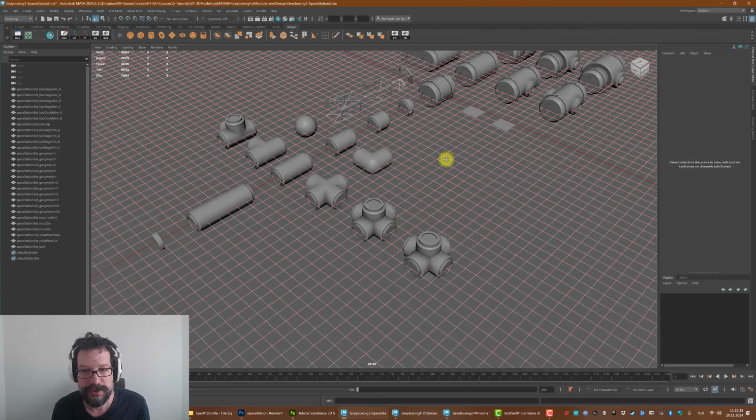So in order to do that, we have to export this, but instead of rendering it one time, or let's say in one orientation, we're going to do a render in both orientations, okay? Now, don't worry about seeing the back faces, because here in Maya, you have to use double-sided lighting, two-sided lighting to light up the surfaces like so.